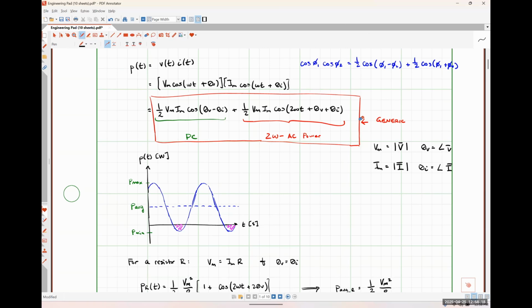So those are the most common mistakes that I see students make when trying to apply any of these equations, is they somehow wind up getting complex numbers inside of these time domain functions, which is inherently wrong. Complex numbers are only frequency domain things. So you should literally just get normal numbers and then a sinusoidally oscillating kind of thing. And then messing up the quote unquote units on the angles can also cause you to get everything else right and just have the phase angle of the resultant be very wrong for my answers. So I just wanted to nip those kind of questions in the bud.